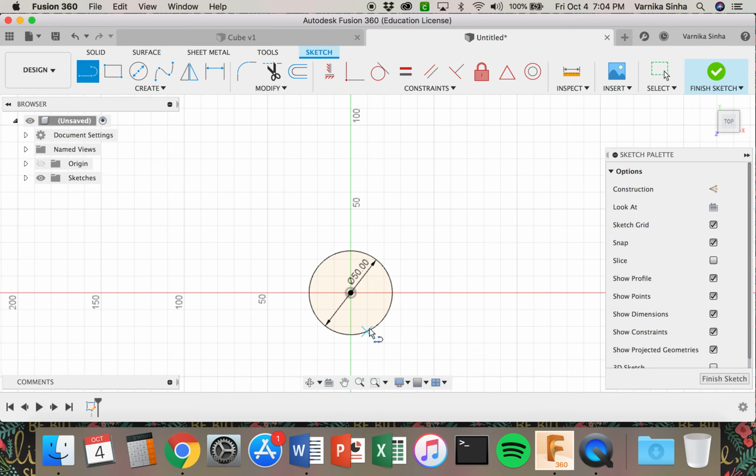If you check this out, one of the great features of AutoCAD is it snaps on. So if I'm anywhere near the circle, it automatically snaps on and makes a blue X saying, oh, do you want to start from here? And I'm like, obviously, yes, thank you. So I'm going to make this right in the middle. That's where it's going to revolve because it rotates around here, right?